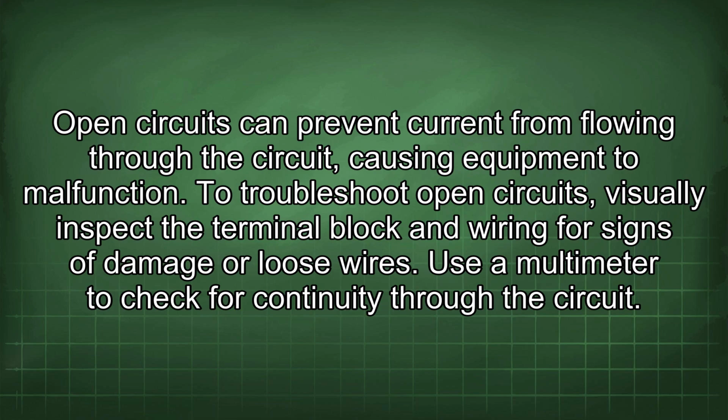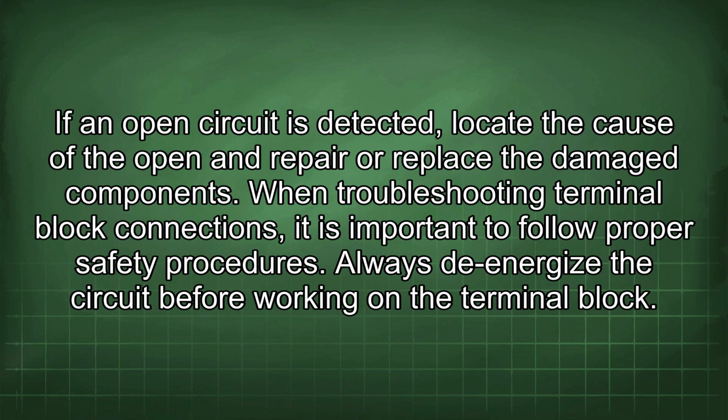To troubleshoot open circuits, visually inspect the terminal block and wiring for signs of damage or loose wires. Use a multimeter to check for continuity through the circuit. If an open circuit is detected, locate the cause of the open and repair or replace the damaged components.